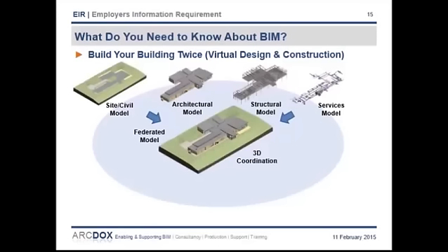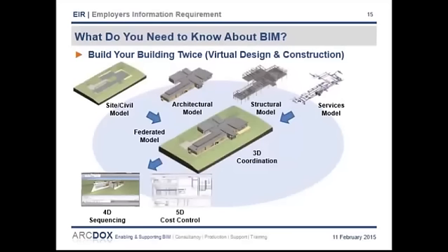Making the BIM process a requirement will force the people involved in the project to create virtual models of their aspects of the design before constructing it, and will help reduce some of the expense and waste on site. But BIM is not just about 3D. The models can incorporate the element of time or the fourth dimension to look at the sequence of construction or issues of logistics and safety, to deal with these issues in the virtual environment where it's easier and cheaper to resolve. BIM can also incorporate the element of cost or the fifth dimension, leveraging computers to quickly and accurately count elements for better cost control.